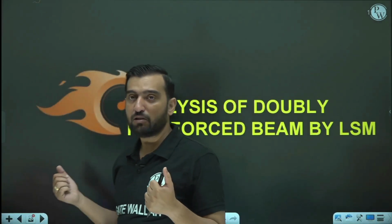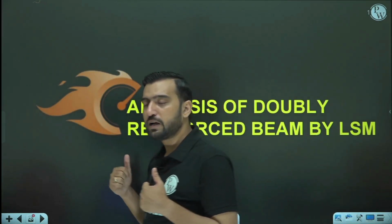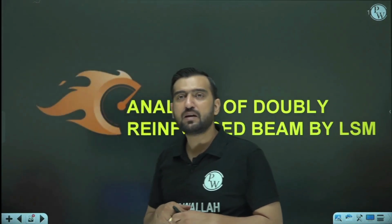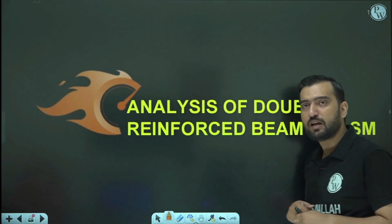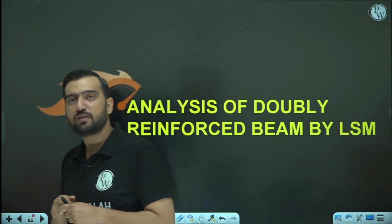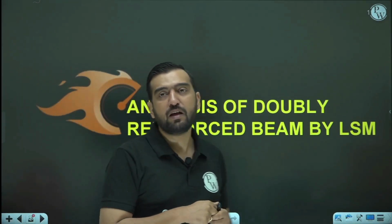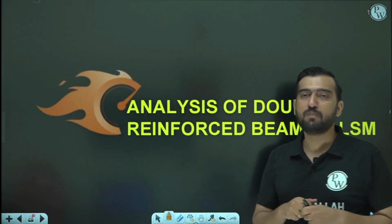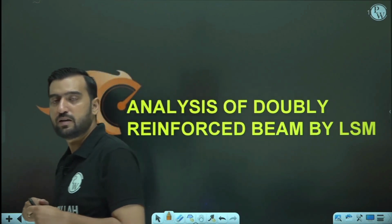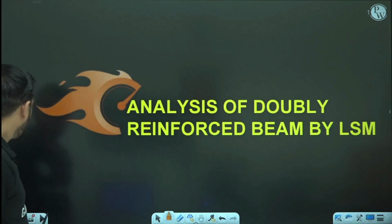Step number 2 is calculation of actual depth of neutral axis, and in the actual depth of neutral axis now we have to calculate the exact compressive forces. Step number 3 is again comparison, and step number 4 as well. Earlier we were equating 0.87 Fy Ast with 0.36 fck b XU, but along with the 0.36 b fck XU, one more component of force will come, and that would obviously be due to the presence of steel, isn't it? So let's proceed with these 4 steps.